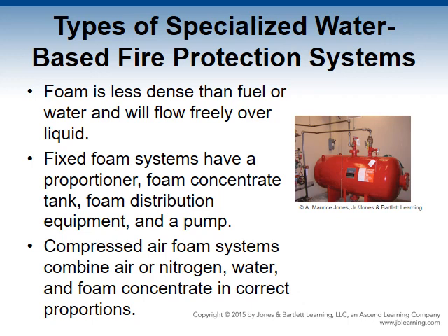Foam products are an effective agent to meet the protection objectives of flammable and combustible liquid hazards. They are less dense than the fuel or water and will freely flow on top of the liquid surface. In order to produce a usable foam, a foam concentrate must first mix with water to produce a foam solution, and those percentages can be anywhere between 1 and 6%. Each percentage represents the amount of concentrate that mixes with water to create the foam solution.